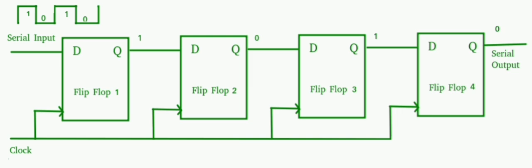R-2R ladder DAC using a non-inverting op amp. Gain of the op amp V0/Vreference = 1 + RF/R1, where RF is the feedback resistance and R1 is the input resistance. Output voltage V0 = (Vreference/2^n) × Σ (i = 0 to n−1) 2^i Vi × (1 + RF/R1).